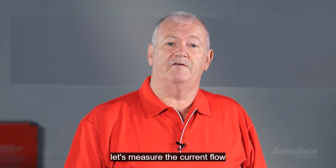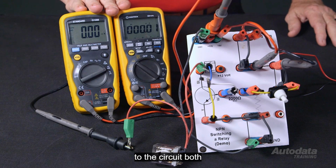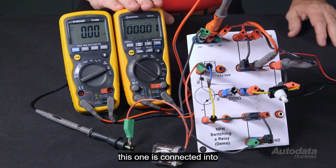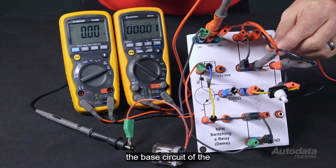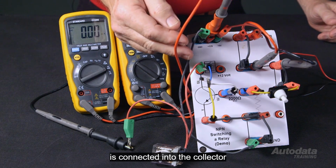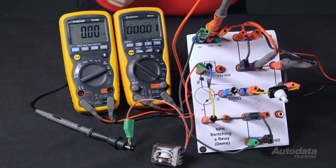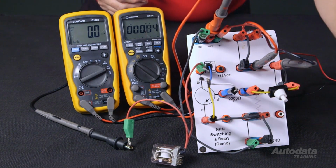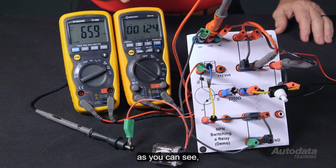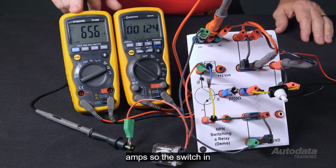Let's measure the current flow in the circuit. I have 2 multimeters connected up to the circuit. Both of them are set to read milliamps. This one is connected into the base circuit of the transistor, and this one is connected into the collector side of the transistor, or the relay coil. I'll turn the circuit on. As you can see, I've got 1.25 milliamps switching about 66 milliamps.